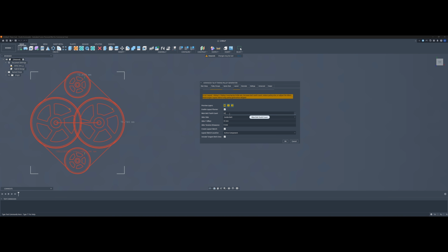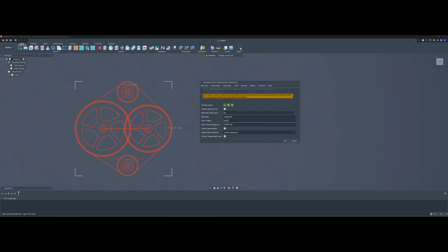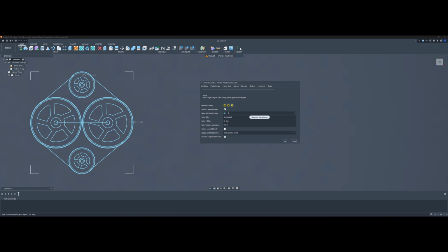If I reduce a value too far, the add-in gives a warning or an error. A warning means generation may still be possible. When the issue becomes a full error, generation is blocked. For layout problems, the preview can show the invalid layout in red instead of simply disappearing. This makes it much easier to understand what failed. The Output tab also shows where the issue is coming from, so you can go back and correct the value. Once the setup is valid again, the warning or error clears.